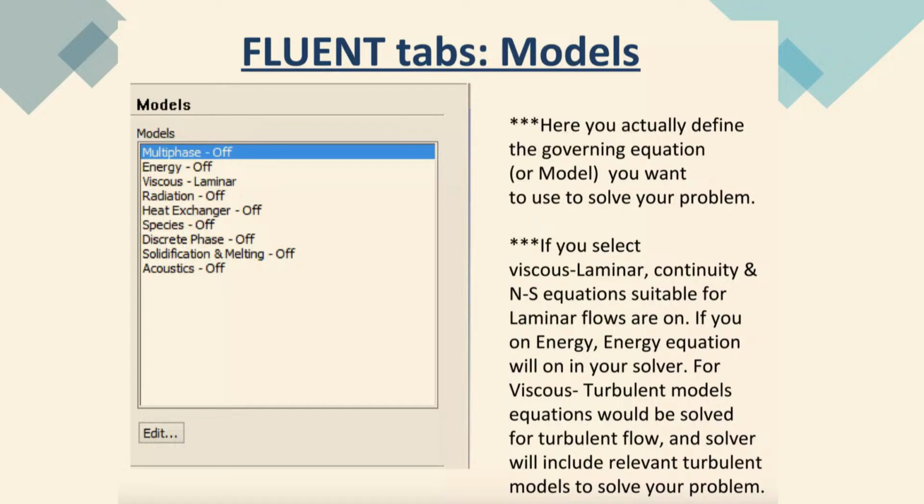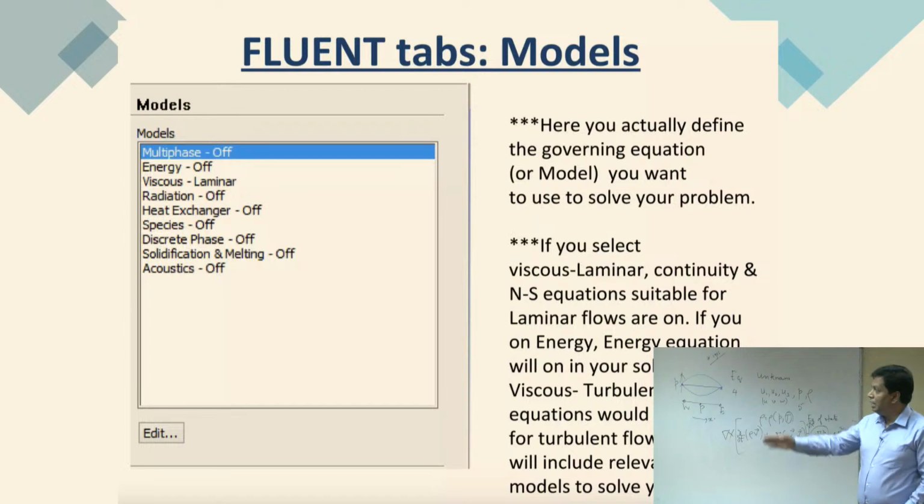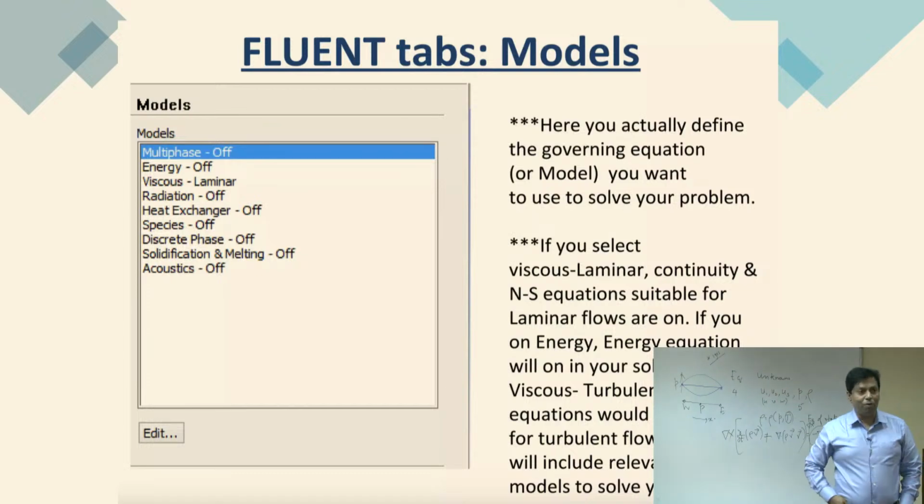Now, energy: are you solving any temperature related problem? If so, just double click and it will be on. And now, viscous: is it a laminar flow or turbulent flow? That is what I said, you need some experience. What kind of flow behavior are you expecting from this problem?